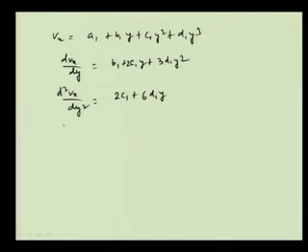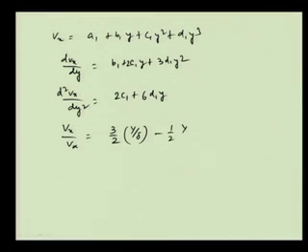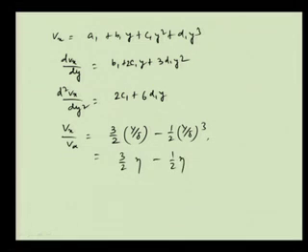and then what we will get is that our expression will be V x by V infinity is equal to 3 by 2 y by delta minus half y by delta whole cube, and this is equal to 3 by 2 eta minus half eta cube, where eta is equal to y by delta, the dimensionless distance along y direction. Okay. And this is a very famous velocity profile, which is a nonlinear velocity profile.